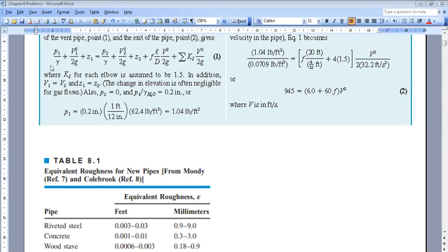So you can say that since D is constant, and we can consider incompressible flow, rho constant, then we can say that A times V is a constant. And since the diameter is not varying, because D is constant, we can say A is constant. So we deduce that V is the same everywhere. Now what will happen,